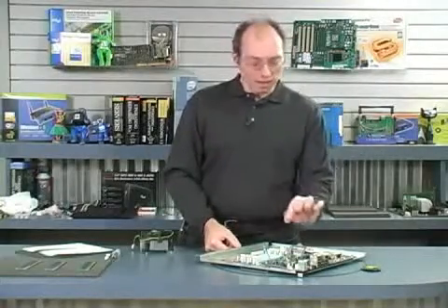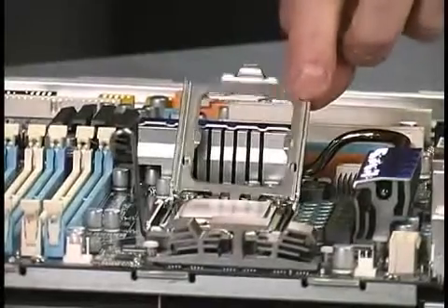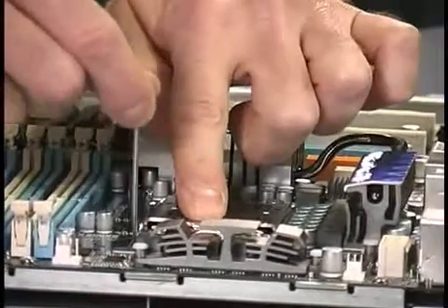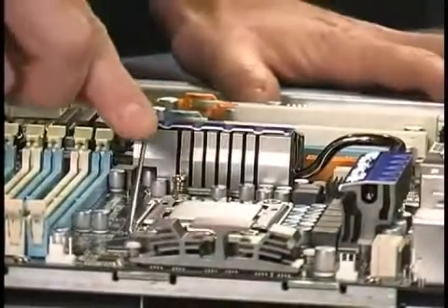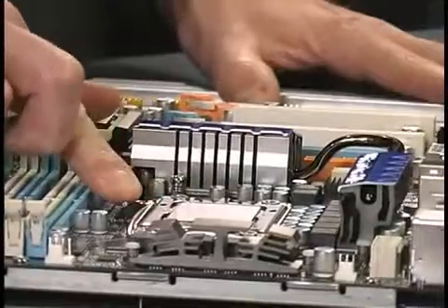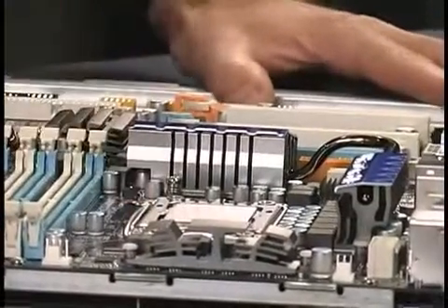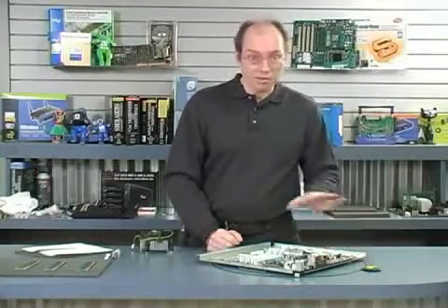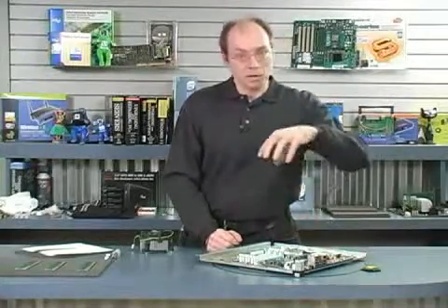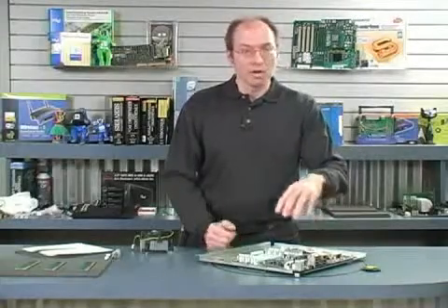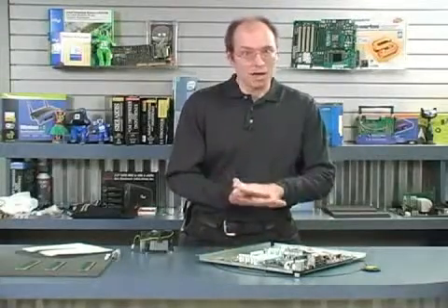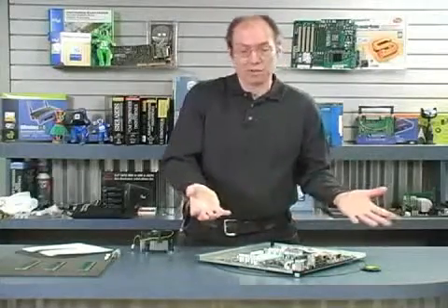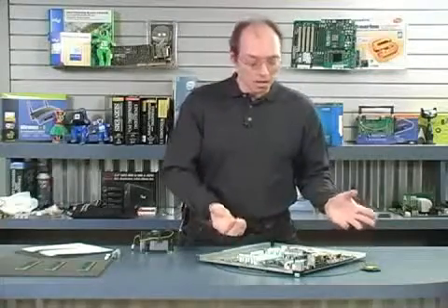However, there's still no tension on it. In order to have it fully installed, we need to drop the load plate on top of it, press it down a little bit, and use this load lever to put all of the tension on it, and then put the lever underneath the retaining tab on the side. So at this point, the processor is now installed in the socket. The load plate is putting pressure onto the top of the processor so that all of the lands on the bottom are in contact with all of the pins in the socket. As you can see, it's fairly simple and straightforward to install a processor.